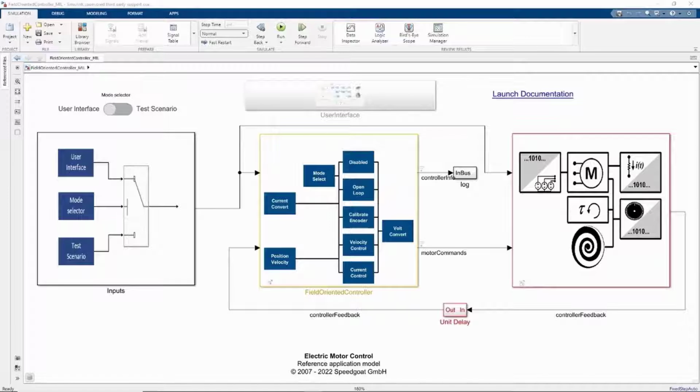The first step to do would be to perform model-in-the-loop simulation. For accurate analysis of the model, you would like your Simulink model to behave exactly like how the real motor behaves, meaning the model becomes a true digital twin of the real motor. This can be done with feeding external input data to the model and tuning the behavior of it.